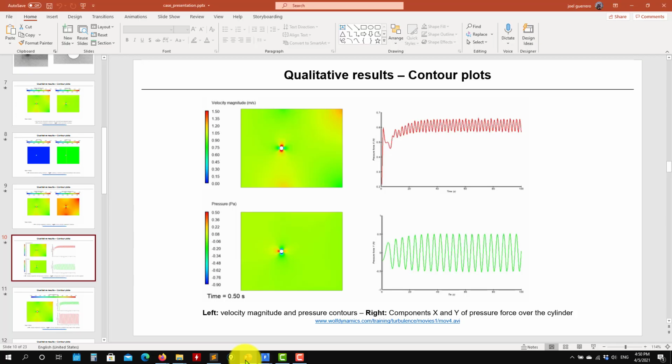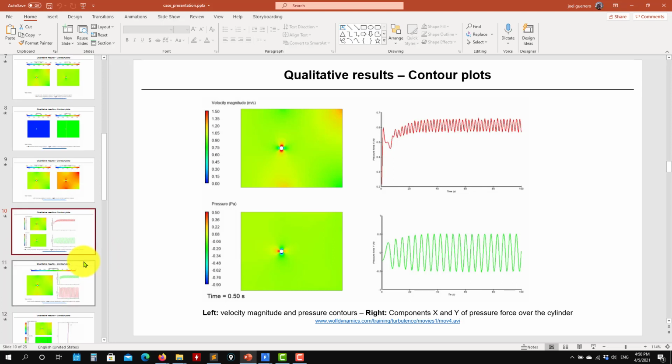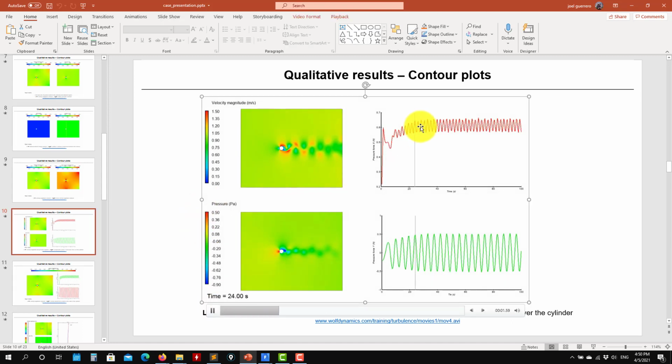Basically, this is important. Later, we're going to do more advanced post-processing for scale resolving, to compute the plot of the energy spectrum. You need to put all those probes there, and then you need to gather the information of velocity fluctuation, or, if you have that, you can add it, get the information of the turbulent kinetic energy. Basically, in those points you put it there and you're just accumulating information.